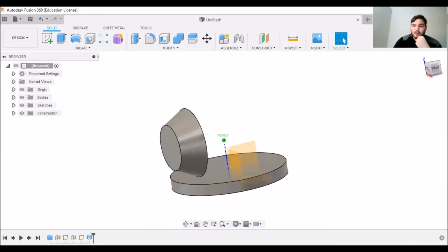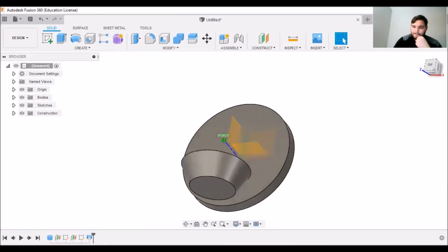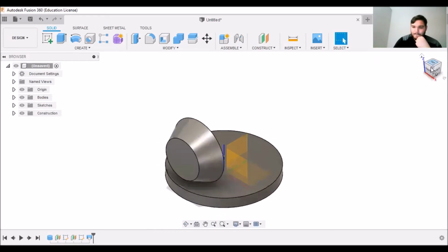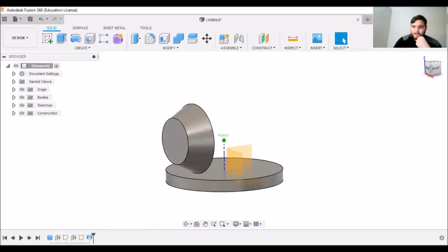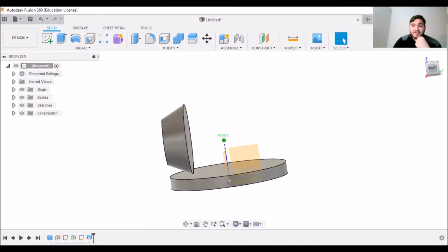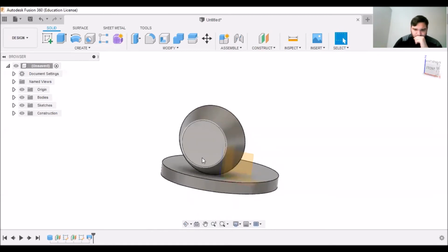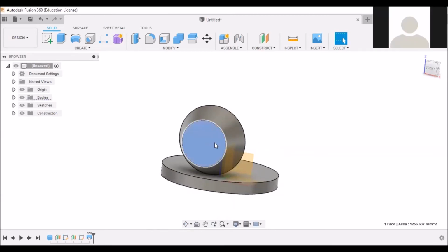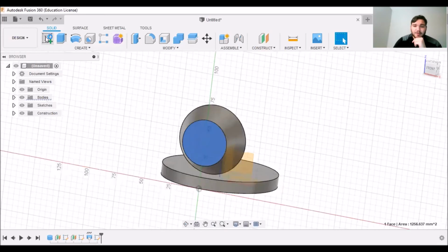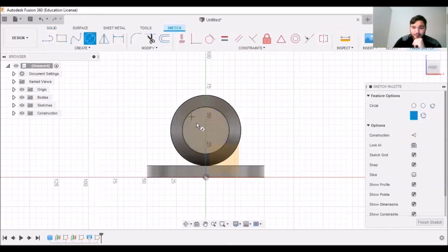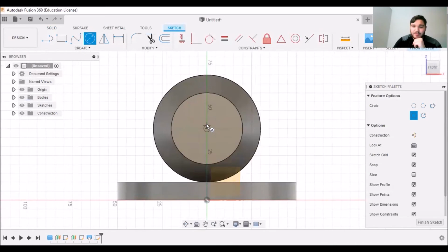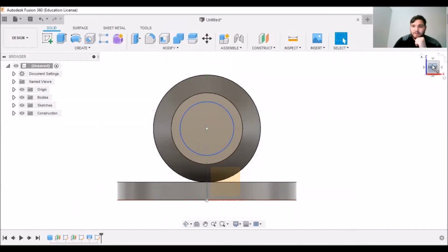Now we have a little joint cap. And so this is basically just a little bitty frustum. And from here, on that smaller circle, we can click on that and create another sketch of an even smaller circle. Same thing, it remembers the center geometry. We can have this one at about 30 for the diameter. Finish sketch.